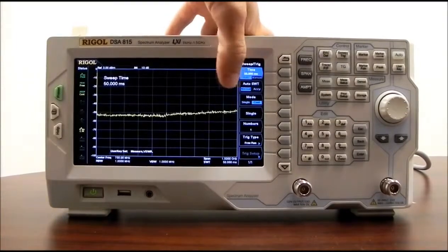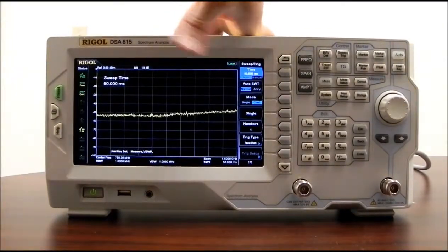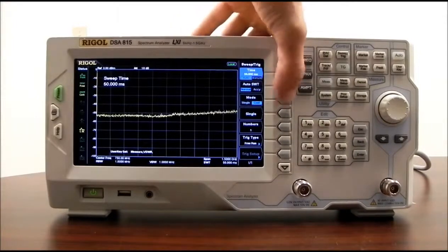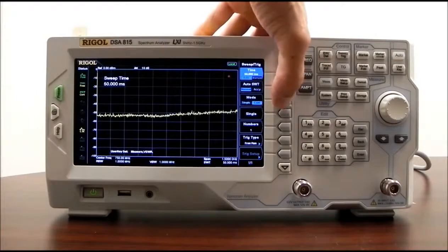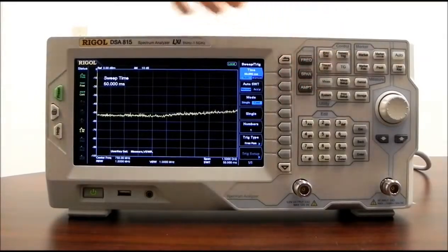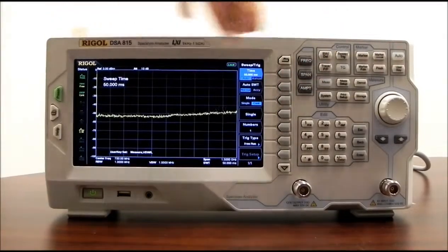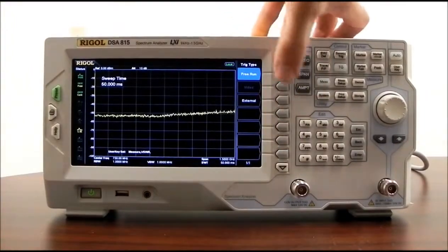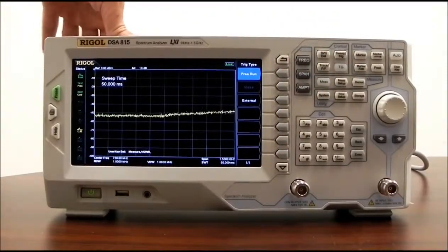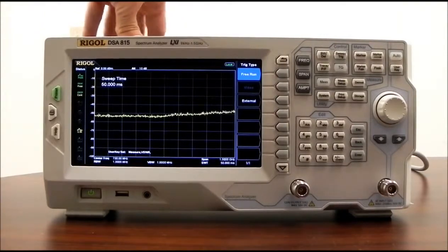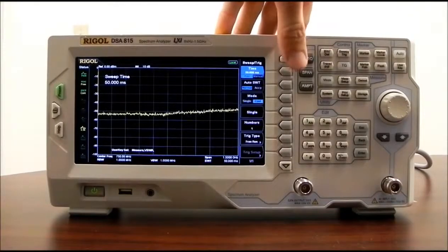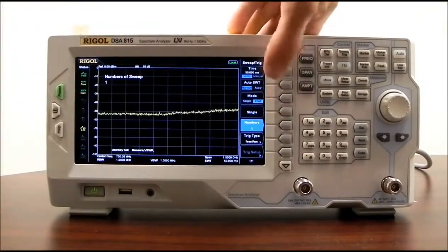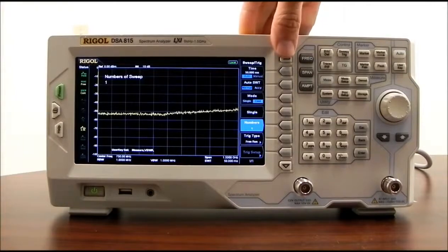We have auto sweep time. We want to keep that normal, or we can go to accuracy mode. Then for mode, we can go continuous or we can go single, and with single we can just press single trigger if we wanted to capture just one image. We also have the ability to do an internal trigger, which is going to be free run, but we can also do external. There is a BNC connector on the back, a TTL level signal, so if you wanted to trigger it in an automated way in order to capture images, you could do that as well. You can set the number of scans per trigger using the numbers key.